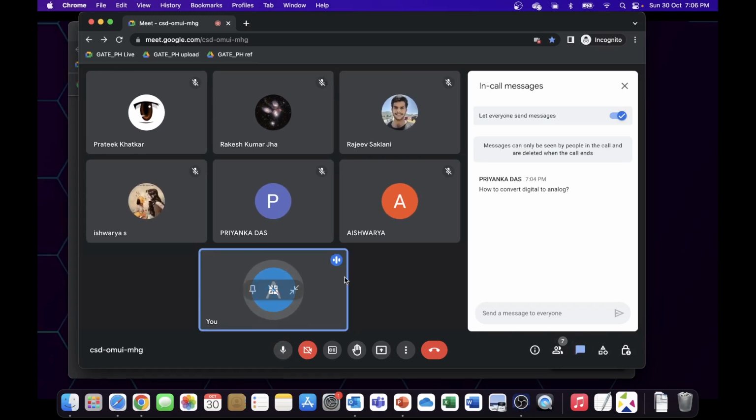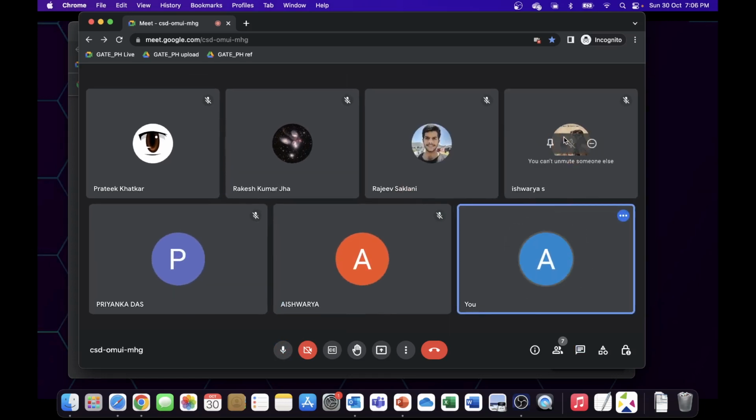There's a doubt about how we convert digital to analog. You see that during op amps we saw that we can add two signals. Similarly, using an op amp, and there's something called an R-2R ladder. If we combine those two circuits, then we can convert a digital signal to an analog signal. Let's take a very simple case. Let's say you want to convert a digital signal 111 into an analog signal. Then you'll have to add.